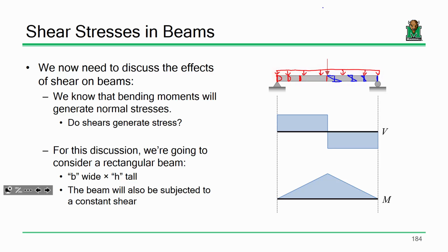So is that physically, like, you cut a section of the beam, that's what the beam's kind of doing. You got a force that's kind of pushing it this way on the bottom. Exactly, yes. If I look at the beam when it's deformed, let's say I zoom in, it's going to look something like that, like it's bent. Okay? So let's say this is the neutral axis. So the neutral axis hasn't done anything. On the top, it's squished together. I can do better now. All right? On the bottom, it's being yanked apart. And it's linearly proportional.